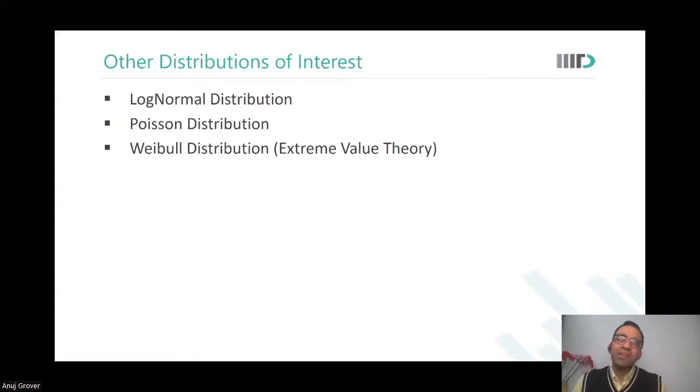Suppose someone tells me that there are 500,000 flip-flops on a particular die. I know 5 sigma would suffice. Why do I go to 6 sigma? So we design based on the quantity, like how big is it? Yes, depending on how big the die and the design are, the number of times a cell is repeated would increase. And that is what should guide you to decide whether you want to go to 6 sigma or 5 sigma, or whether 3 sigma is sufficient.